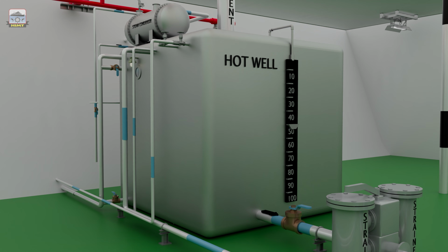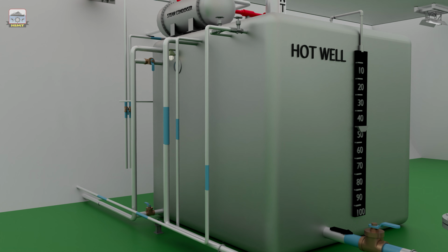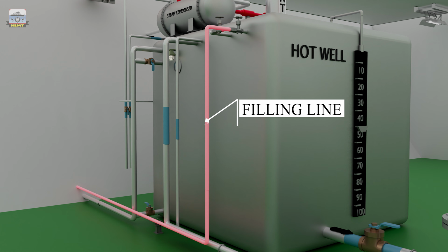The steam is consumed in systems such as steam blast jet type of burner for atomization purpose, whistle, soot blowers, etc. Due to the shortage of the condensate received by the hot well, makeup water must be added into the hot well. For this, a filling line is provided from the hydrophore.